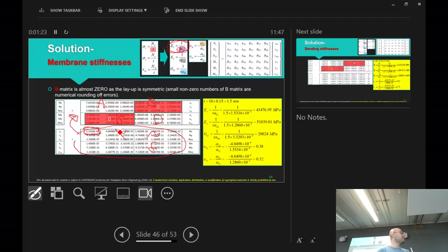So what is the EX of the whole laminate? The entire laminate. Essentially we are trying to smear the stiffness of the plies and see that laminate as an orthotropic material, as a plate, like an aluminium plate. So you kind of just turn it into one thing. Yeah, so I want to find out, to make the calculation easy, what's the EX and what's the EY or modulus.